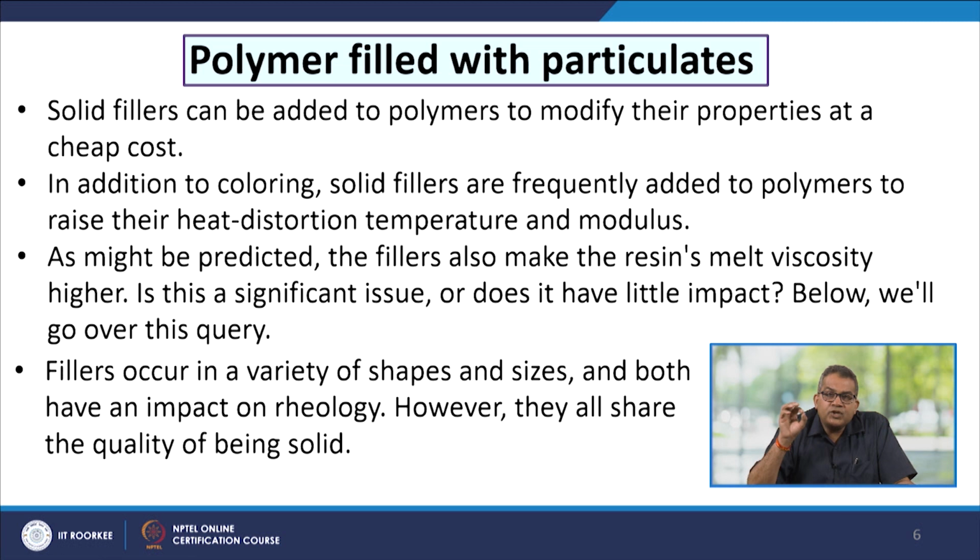In addition to coloring, solid fillers are frequently added to polymers to raise their heat distortion temperature and modulus, and sometimes the mechanical, thermal or chemical stability. As might be predicted, the fillers also make the resin's melt viscosity higher. Is this a significant issue or does it have little impact? Below we are going to go over this particular query.